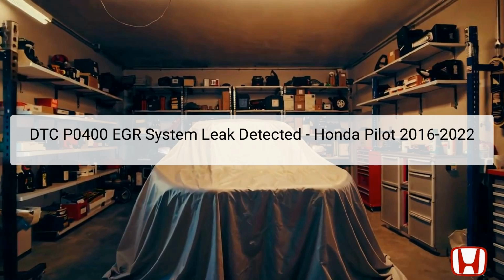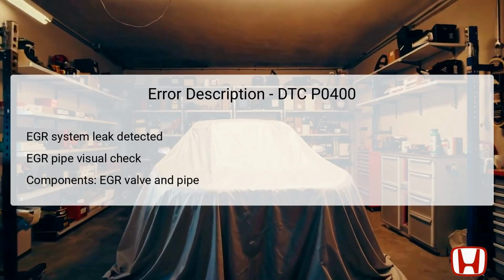The EGR valve, typically located between the intake manifold and the exhaust manifold, regulates this flow of exhaust gases. A leak in the EGR system can lead to improper engine operation, poor fuel efficiency, and increased emissions. Before proceeding with any diagnostics, a thorough review of the general troubleshooting information is recommended to ensure proper protocols are followed. The error description for DTC P0400 indicates an EGR system leak, which can hinder the system's performance.